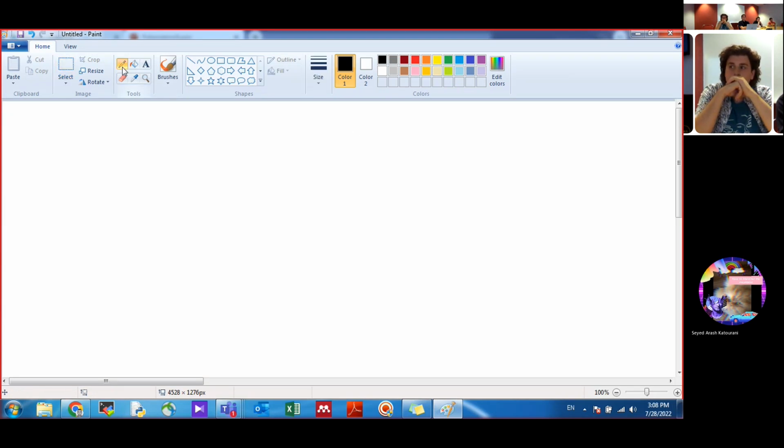Do you use vias when you connect your source and drain? Vias and wires, yes. How many vias do you use? Normally it's 1 or 2 vias, and it's all about the space you've got. Normally I only use 1 or 2 to clear the DRC of minimal metal area.